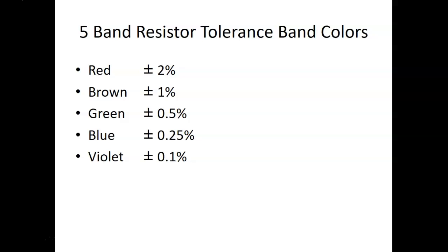A resistor will never start with black, gold, or silver. If it starts with any of those 3 colors, you need to just say no. They don't exist. If you start with black, that's like starting with 0. Gold and silver, you're probably reading the tolerance band first. Flip it around.